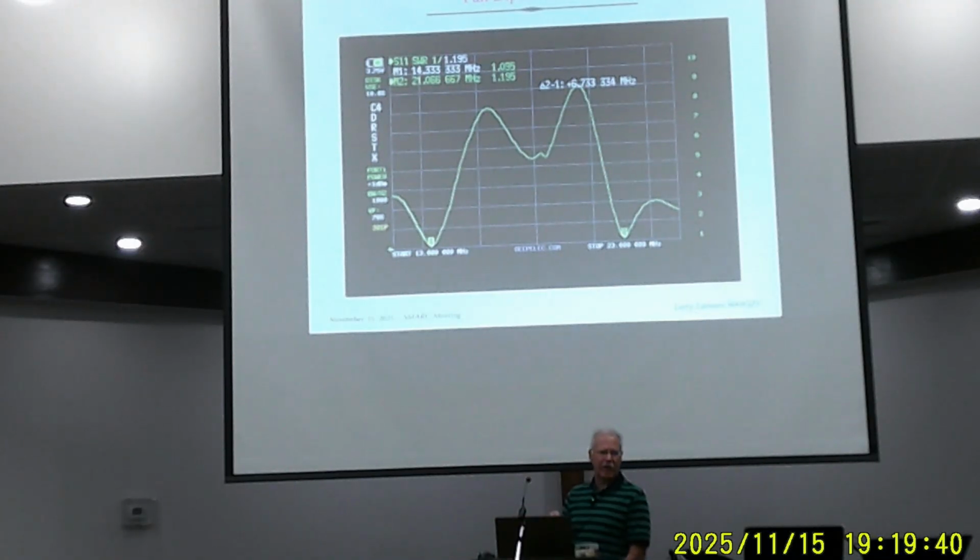So if you ever mess with dual band anything, some kind of law of the universe is that if you make one better, it makes the other one worse. So if this was like 3 to 1 and 2 to 1, and you have somebody helping you, you can be looking at that and say, well, the one that's 3 to 1 SWR, trim this or lower it or do something. And while that's being done, you can see what happens to the other one. So as you decrease that, the other one may go up. But this is pretty much real time. You're seeing the sweep as it's being done. So that's real handy. There may be a particular special case, but it's nice you can see what's going on as you're doing it.